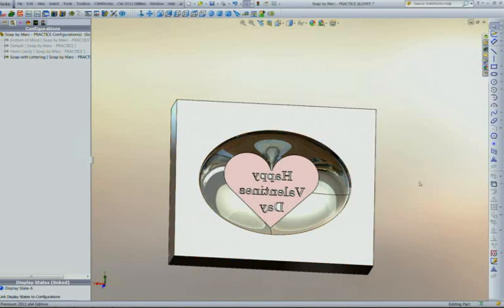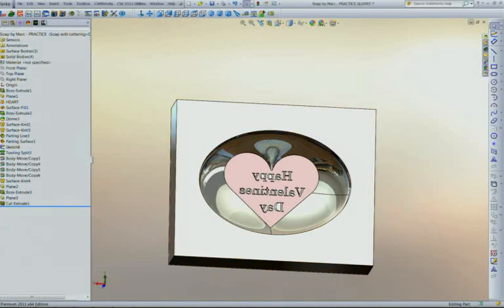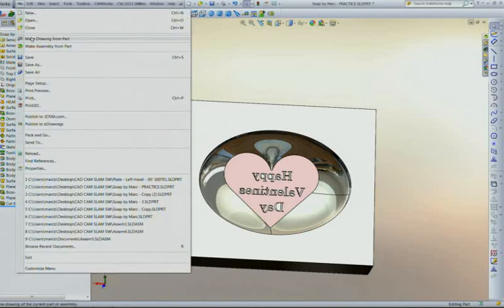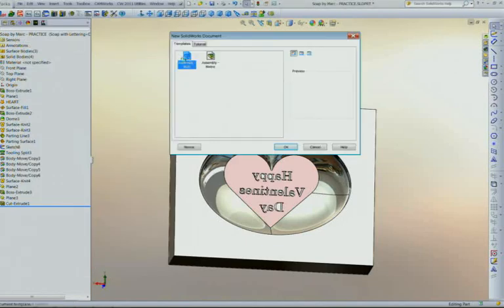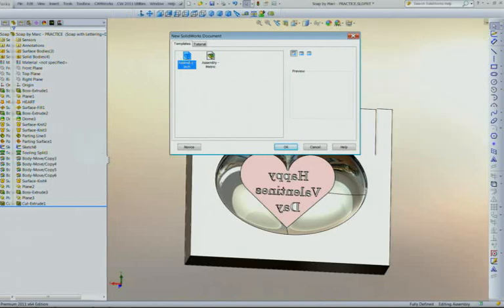So these letters will be easiest put into the bottom of this cavity using an electrode, an EDM sinker electrode. And so what we'd like to do now is take this file over into assembly and create an electrode using a new product called ElectrodeWorks.